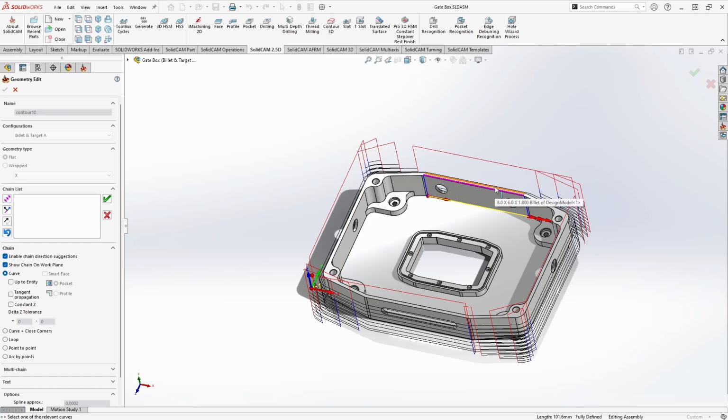The reason this is important is because technically you can select lines that would be straight vertical, and those are not going to appear when you project them up onto your XY plane. So we can see our original selected contour in yellow here, and the projected contour in pink. We'll also note these red arrows. These are going to indicate the direction the chain is going to be created in. And that'll make more sense as we start selecting subsequent line segments.